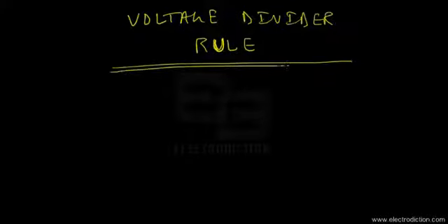Welcome to a tutorial on electronics. In this tutorial we're going to discuss the voltage divider rule. Okay, so this rule could be derived from Kirchhoff's voltage law. So we'll do the same over here in order to display how this rule is very useful in terms of circuit analysis and determining how voltages are divided amongst various circuit elements.